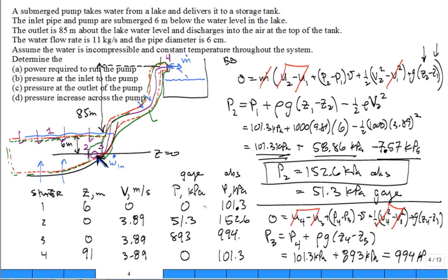893. So looking at the pressure, it's very high at the outlet of the pump. That's the highest pressure. Okay, I'll try and tuck it in this space right up here. What is the pressure increase across the pump? The delta P across the pump, that's just the pressure outlet minus the pressure inlet. And that pressure change across the pump is 841 kilopascal.